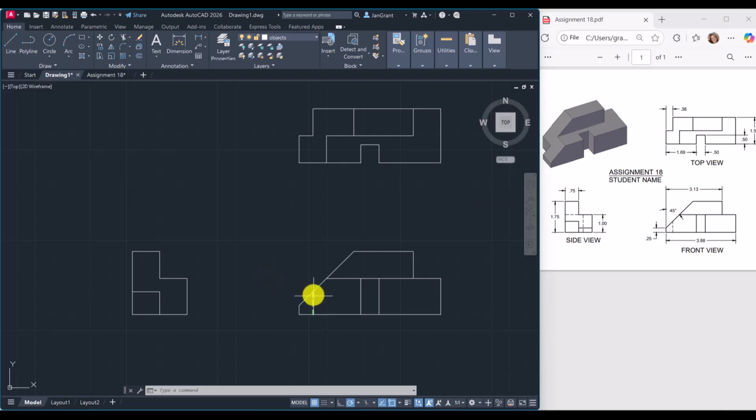So the top of this hidden line is actually this little box right there. And now we have another line right there that represents the 0.25, this thinner triangle. No, rectangle. Let's start the line command. Rest your pointer at the top of this 0.25 line, pull your mouse over and click, and then over here and click, right click and enter.